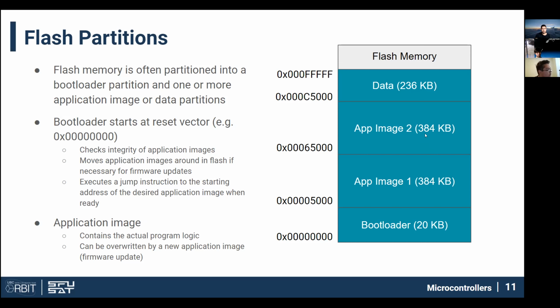In the case of Eliasat, the way we've set it up is there's a bootloader and then there's an application image on the internal flash. There's just one. And then on external flash, we have an external flash storage chip with some additional slots for application images that are going to be updated onto the internal flash, and just a backup image if something goes wrong with the one in internal flash. So it's very customizable to the particular use case.